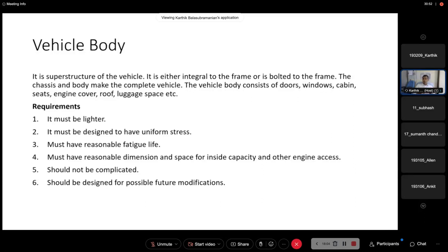So that is how, when people started slowly seeing that a proper combination of the vehicle body and frame needs to be achieved, they ended up with what is called the integral body or the unibody structure. They felt that there is no point in having separate vehicle body and the frame. Let us integrate the two. But when the requirements for a separate frame and vehicle body still existed, they made the frame extra rigid so that most of the torsion is just taken up by the vehicle frame only and not by the vehicle body.